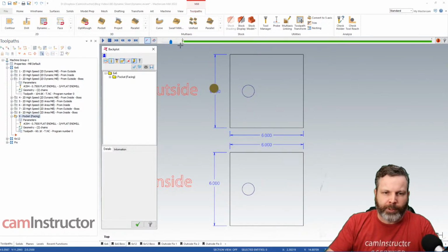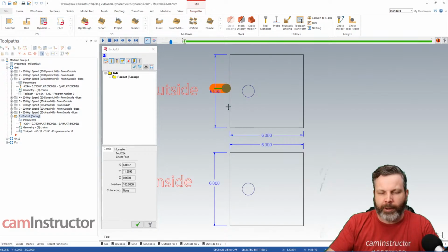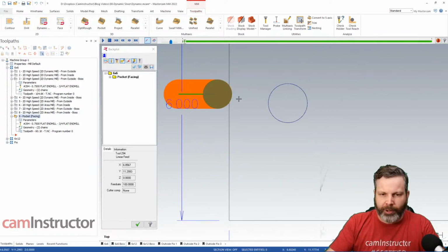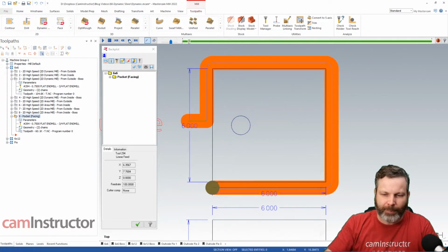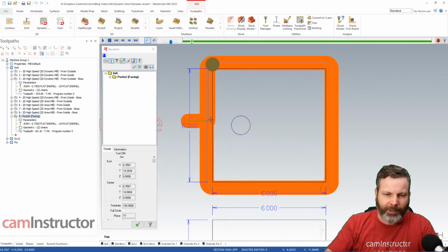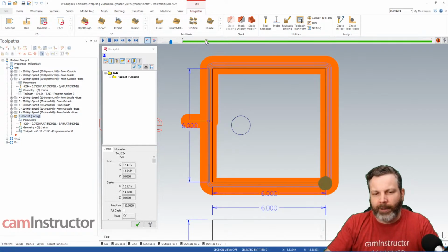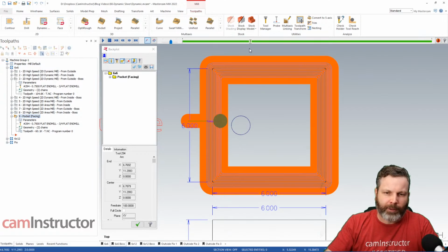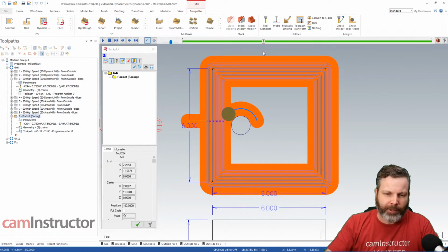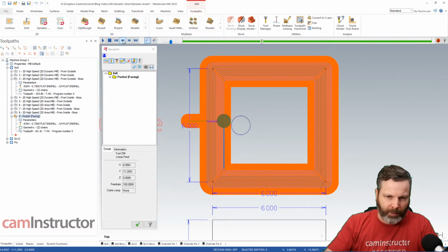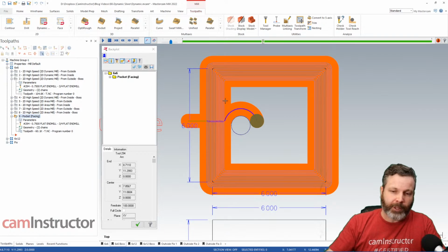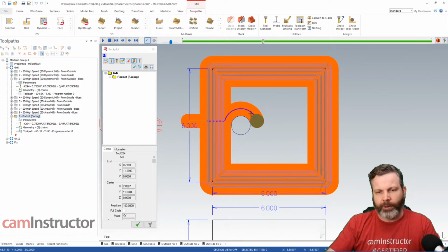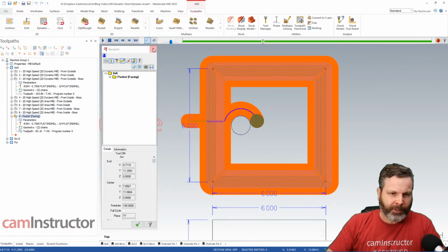The problem with this tool path, you can see it right off the bat, is a straight dive into material. If you're running at 100 inches per minute, 1.5 inches deep, it's probably not going to go so well. Same with those little transitions in there. Pocketing is not a tool angle controlled toolpath, and I think the biggest problem is right there. If we were feeding at 100 inches per minute, cutting 1.5 inches deep, and we did something like this with our tool, that's an instant break.